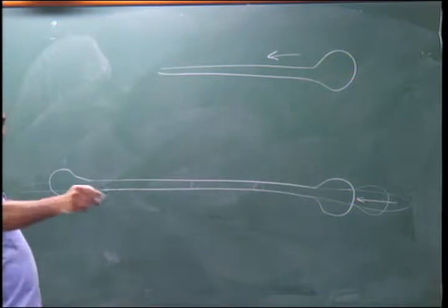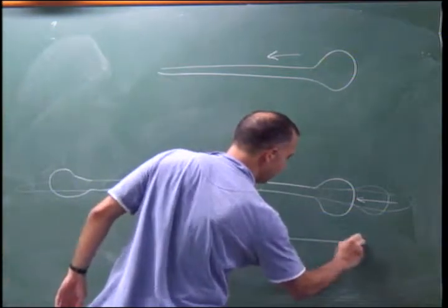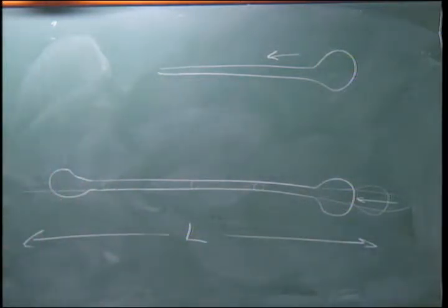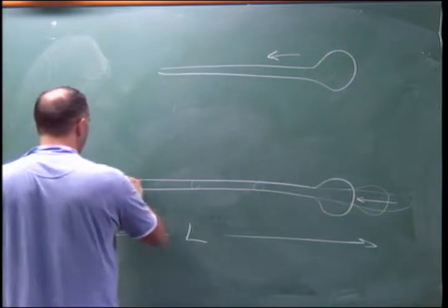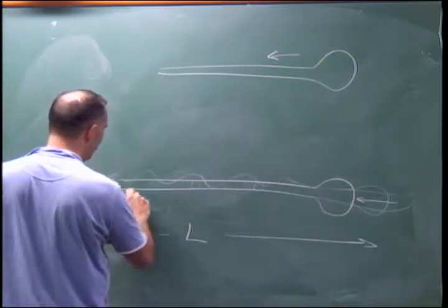So I want you to calculate that speed, and then if you have the initial length of the filament, you can predict how long it's going to take to collapse, and then you can compare that to the Rayleigh-Plateau time, because if we're starting with a cylinder, it wants to go unstable to Rayleigh-Plateau. So the question is, which is going to win? When are you going to get just one drop, or when are you going to get a whole bunch of drops?